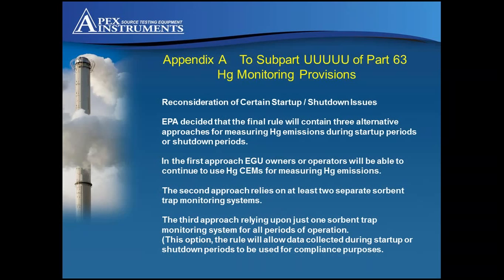Appendix A really takes you, the plant owner operator of the sorbent trap monitoring systems, to an area where you've got to consider your monitoring strategy. Within Appendix A, we start to see the definition of monitoring system installation requirements, primary and backup monitoring systems, redundant backup systems, non-redundant backup systems, and temporary like-kind replacement analyzers. And perhaps importantly, for how long we can use non-certified systems.